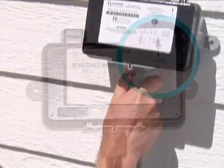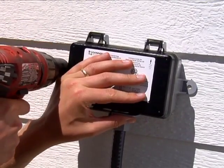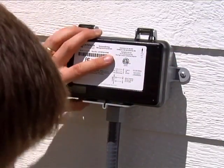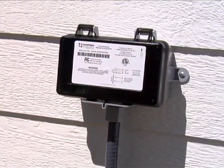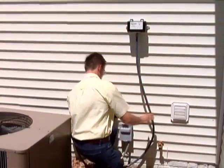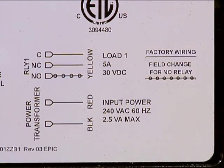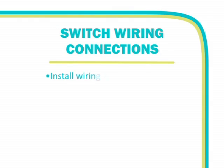Mount the switch with this label up to ensure a rain-tight rating. If you are installing the switch on an irregular surface, do not tighten the screws, as this may cause the mounting tabs to break, which can defeat the rain-tight seal. Wire the switch according to the diagram located on the switch. A copy of this diagram is also in your student manual. Install the wiring within a half-inch liquid-tight, non-metallic, flexible conduit, or make sure the wiring is close-nippled into an approved junction box or wiring compartment.